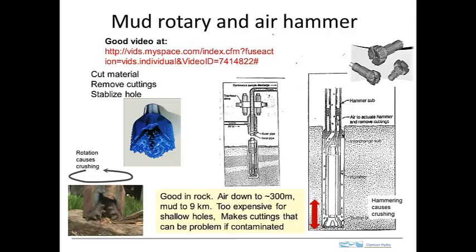So you just simply can't cut rock in shear with this shearing type of motion. And so what's done instead is to create the cuttings, to break the material, by crushing it. And that's done using a bit like this. This thing here is a tricone bit, and there are 3 cones on it. So there's one cone, there's one cone, and there's another cone over there. These cones rotate as this bit rotates.